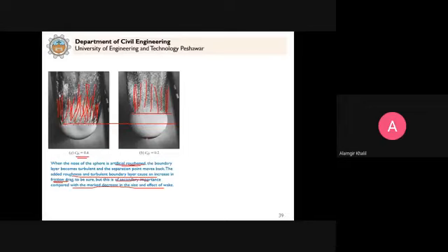Of course this will increase the friction, but this is the most important thing that has occurred. As a result the drag coefficient is reduced to 0.2 as compared to 0.4. So as compared to smooth, with roughing the surface this body will move faster through the water as compared to this body. Clear?